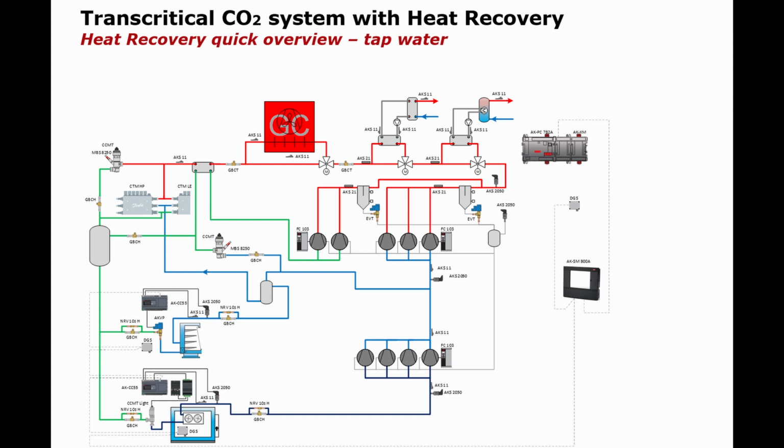In the controller, we have the control of the gas pressure, so the system is able to reach the optimum COP even when the heat recovery is also taken into account. It's very important to say that the cooling system has always priority over the heat recovery to ensure maximum COP. The controller allows to use one or two heat circuits, depending on the needs. It can be hot tap water only, heat reclaim only, or both circuits.